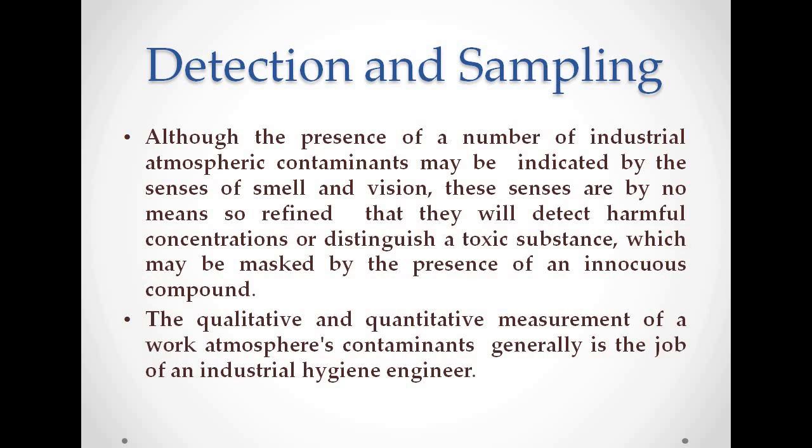Now, how to detect and sample? Although the presence of a number of industrial atmospheric contaminants may be indicated by the senses of smell and vision, these senses are by no means so refined that they will detect harmful concentrations or distinguish a toxic substance which may be masked by the presence of an innocuous compound. The qualitative and quantitative measurement of a worker atmosphere's contaminants generally is the job of an industrial hygiene engineer.